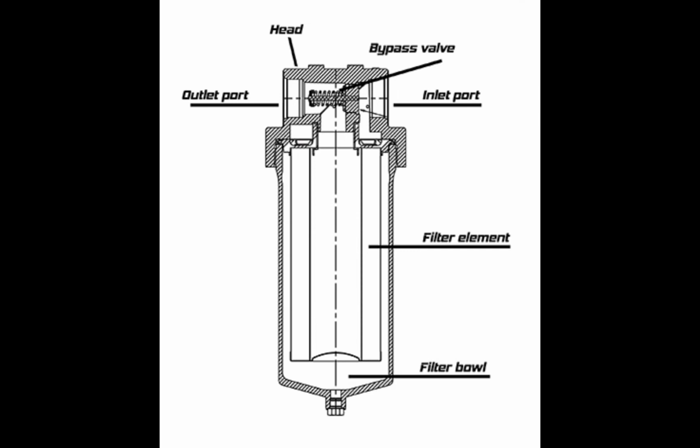What happens to the hydraulic fluid flow if the filter element becomes clogged with foreign material? Bypass valve will redirect fluid from the inlet port to the outlet port. What would cause a hydraulic filter to go into full bypass mode, allowing unfiltered fluid into the system? Clogged filter.